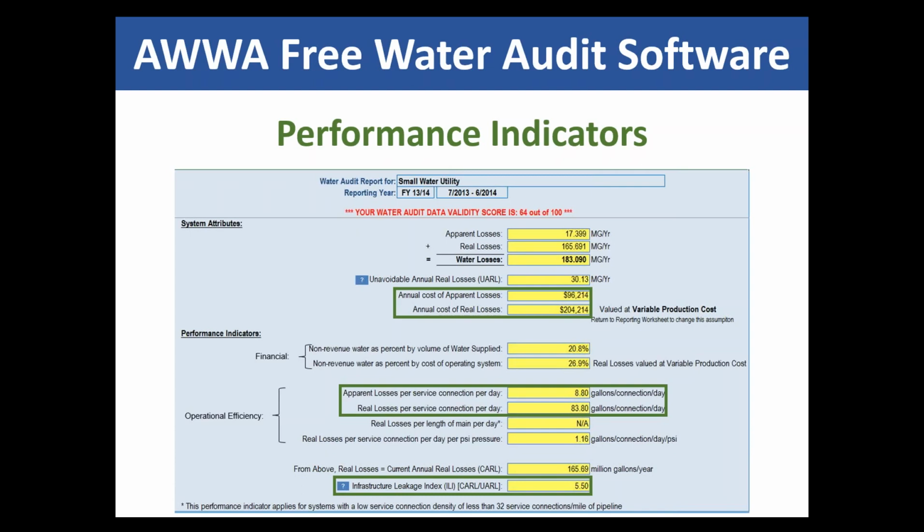And so the infrastructure leakage index is the ratio of your actual volume of leakage that you calculate with the water audit, those billion gallons for LADWP, compared to the calculated technical minimum. So it's a modeled figure working with your infrastructure. So when you report miles of mains and service connections, that is incorporated here, as well as your operating pressure. If you're running 95 psi in your entire system, you're going to leak more just naturally than a system that runs at 60 psi.